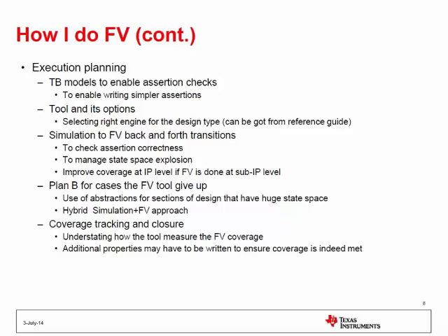And the fourth point I would like to say is have a plan B, because if you don't have a dedicated formal verification team and you are doing both your simulation and the FV, you need to plan for a plan B in cases where the tool gives up, because you will have an end date and somehow you need to meet it. You need to have a red point saying, okay, beyond this point, if I continue on the formal side, I'm not going to be successful. You need to have a plan B and then move to it.